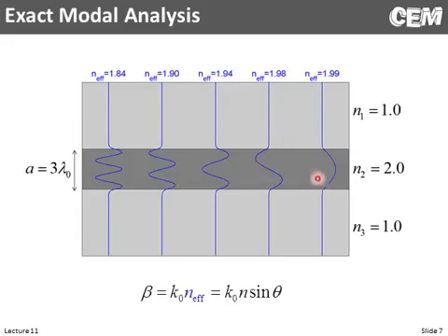modes look like. We have what we call the fundamental mode, and we know that because it has 1 hump. Second order mode, there's 2 humps. Third order mode, there's 3 humps, 4 humps, 5, and so on. Now, when we analyze a waveguide, we're actually going to calculate many modes. But it turns out only a few of them are guided.